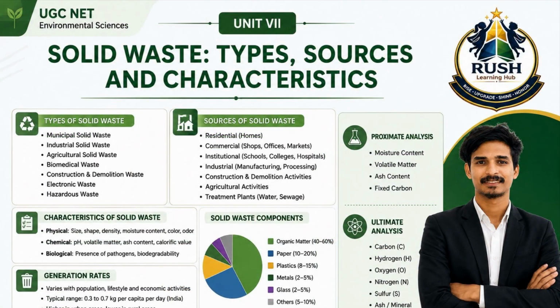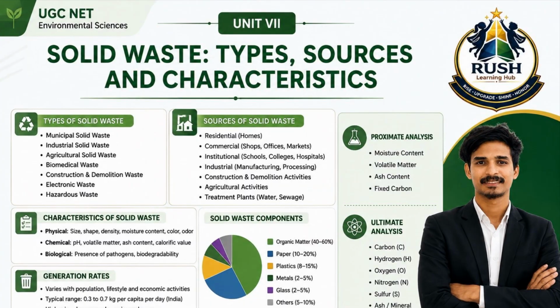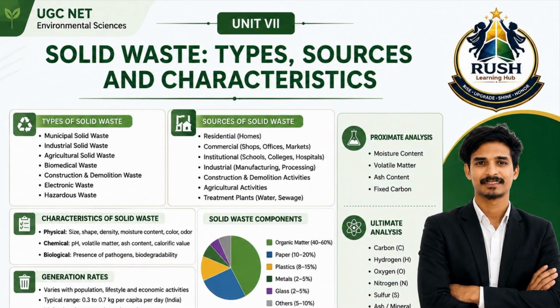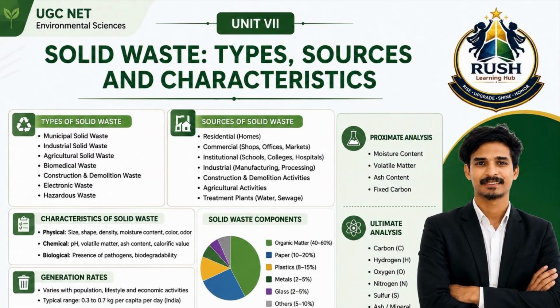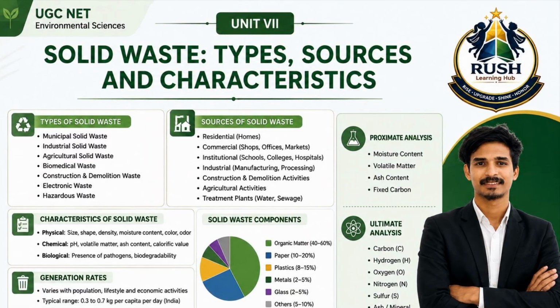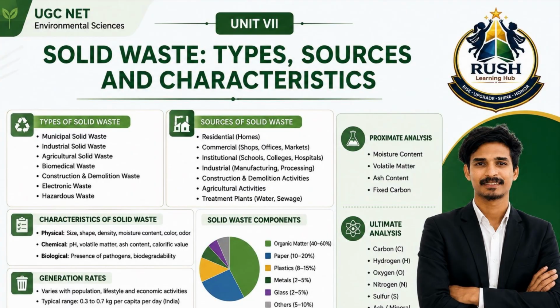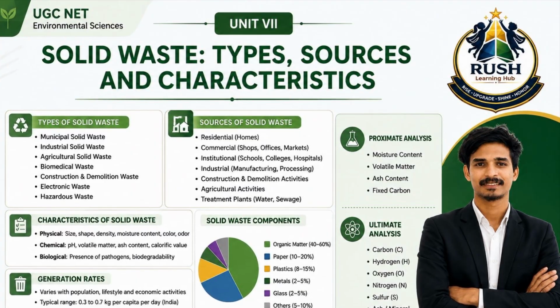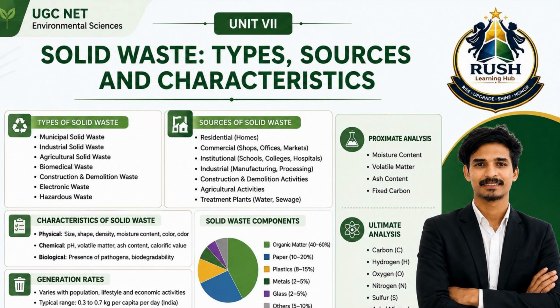Moisture content is particularly important because waste with high moisture is suitable for composting and biomethanation but less suitable for incineration. Density affects transportation and landfill design, while particle size influences recycling and biological treatment processes.